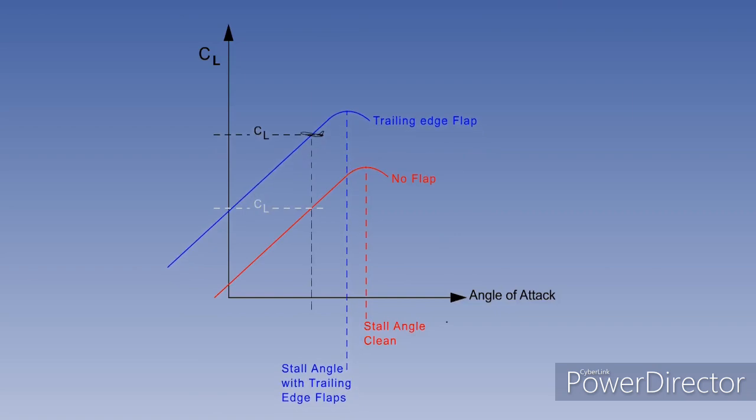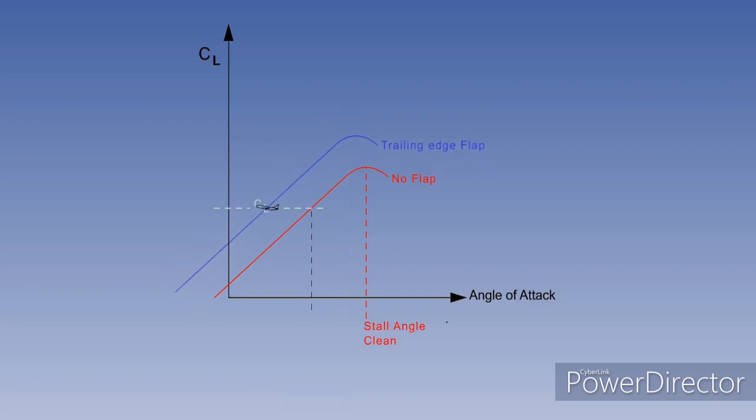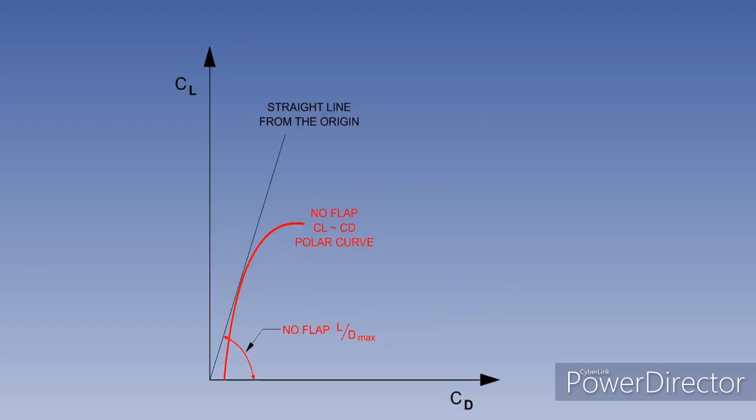When the pilot lowers the trailing edge flaps, the wing camber is increased, and if the pilot did not prevent it, lift would increase. As the flaps deploy, the pilot must reduce the angle of attack so that the effective angle of attack remains constant and that lift still equals weight. Please remember that any amount of flap will increase drag.